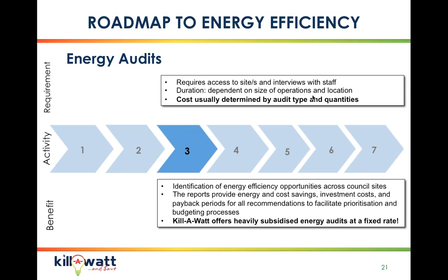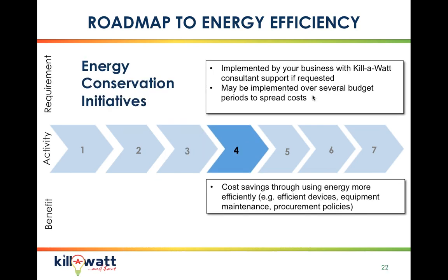Okay, energy audits. Now, energy audits can be done in many different versions. There's a lot of information online. A lot of people will do just normal turn light switches off and air conditioning and so forth. The kilowatt program, we have proper auditing assessors that will come to site, and they do a full review, either a level 1 or a level 2 audit, and follow up with a report, and that then gives you all the information of where your energy opportunity savings are and what you need to do about it. Also includes some information about return on investment, which is handy. A lot of the information we get is based around changes of people's patterns, not necessarily massive capital investments.